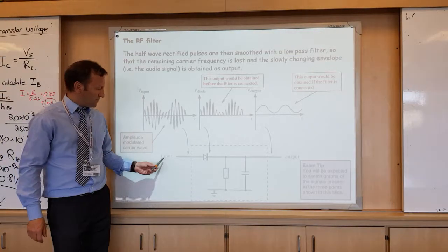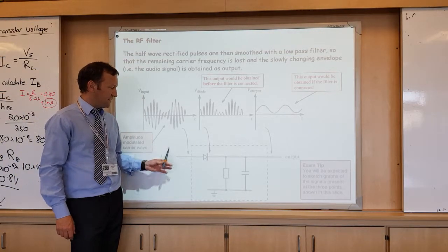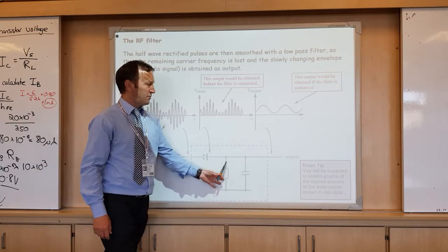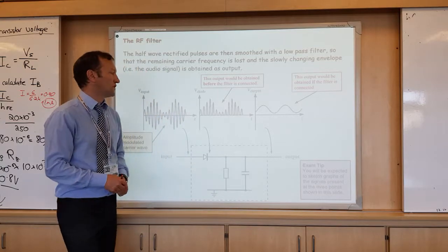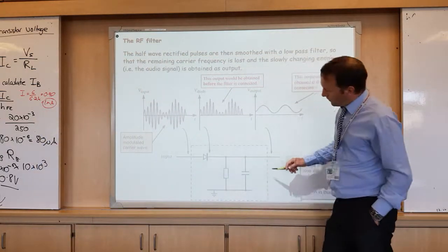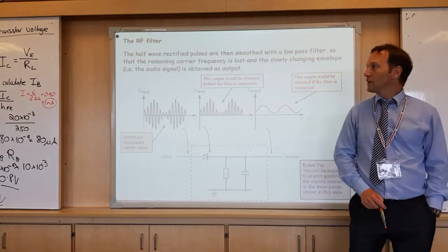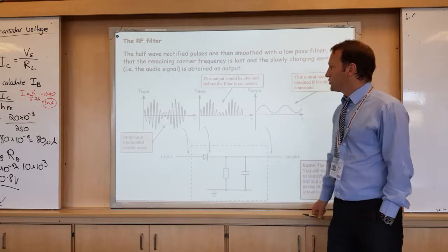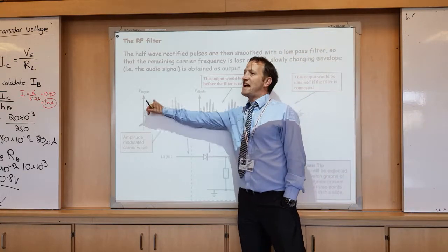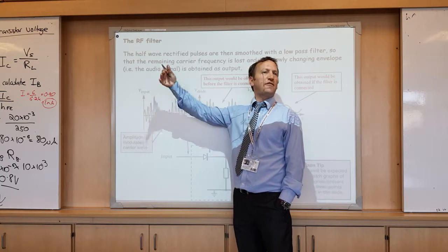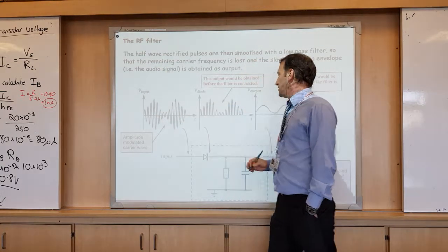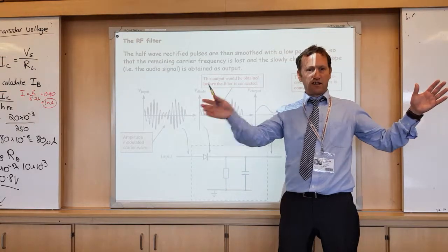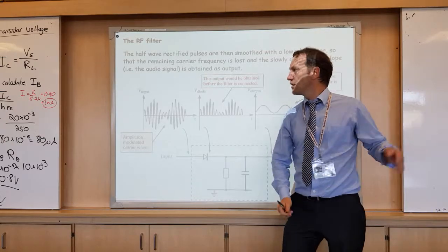So the circuit diagram is as simple as antenna, tuning circuit, diode, low pass filter, and then output. Okay? Sometimes they give you questions on the low pass filter. If you think about the transmission, the break frequency of the low pass filter should be above the frequency of the sound, so above about 5-10 kilohertz, but below the frequency of the carrier. So you've got the audio signal and the carrier, you need to split them, so it needs to be in between the two.